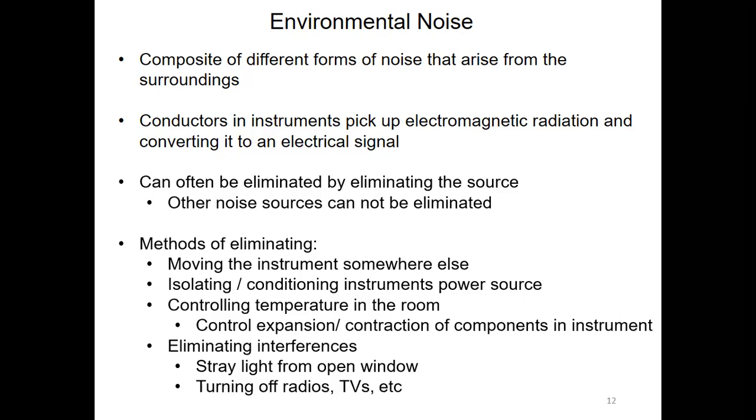So what we can do here is either recondition the power sources, and also if there's a possibility, keep the power sources a little bit away from the instrument. In that case also, we can get rid of this instrumental noise.